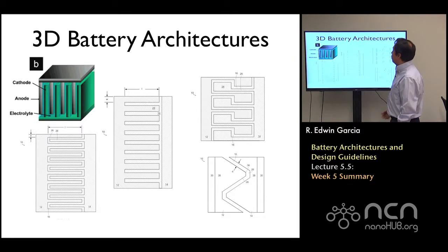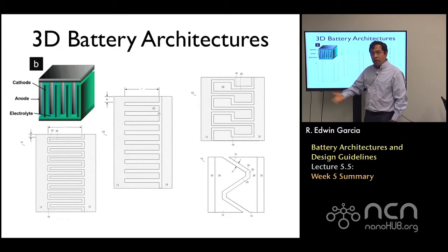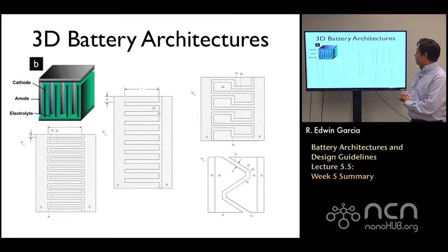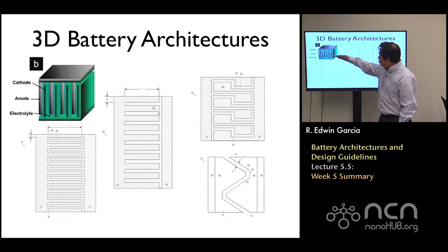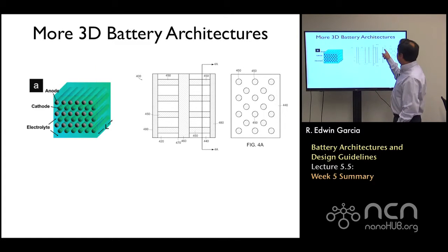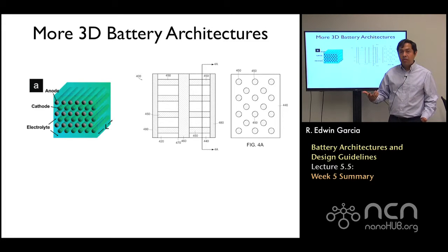This leads to the concept of a 3D battery architecture, where basically by removing the electrolyte carbon binder mixture and instead putting this electrolyte layer in between, you can basically exchange lithium directly through very short distances. Okay, and here you can see different architectures as we have discussed them, each of them having their potential advantages and disadvantages. Okay, in this case you can see these layered structures, or you can think of, for example, these rods, where one, say, cathode rod would be in the neighborhood of a set of anode rods, so they can exchange sideways lithium with its surroundings.